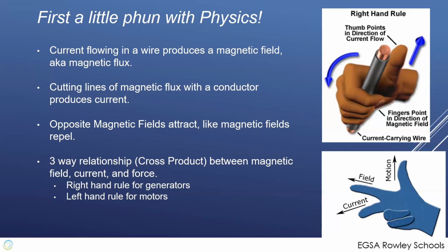Electron flow, technically, is electrons flowing out the negative terminal and into the positive terminal. And many places for a long time taught electron flow that direction. One of the places that taught it was the military. I don't know which branch or which area, but I have had students in the class in the past that were taught electron flow. Throughout the classes today, we all use conventional current flow. So my right-hand thumb analogy, my right-hand cross product that we're going to use for the definition of an alternator's physics, will be based on conventional current flow. So if you don't know the difference, you're trained in conventional, don't worry about it.